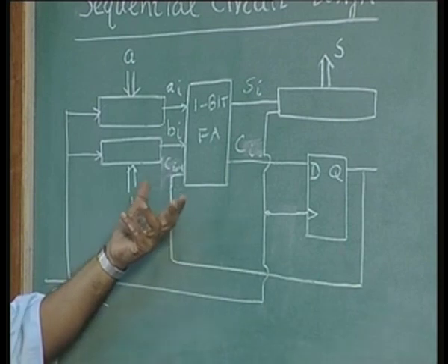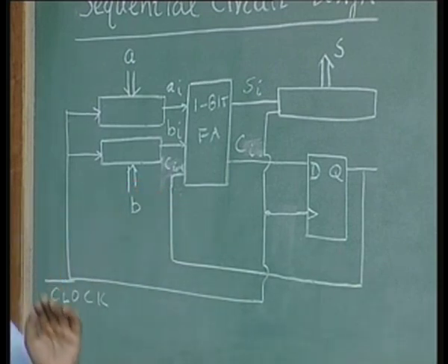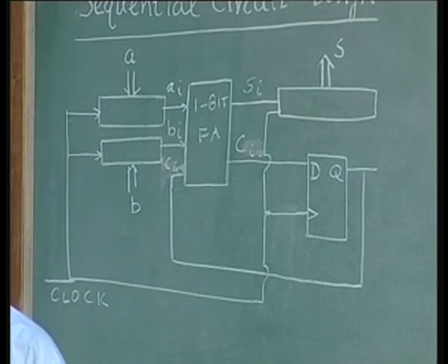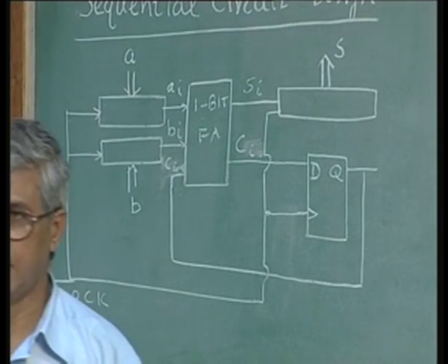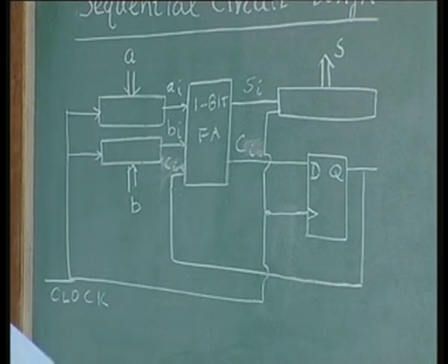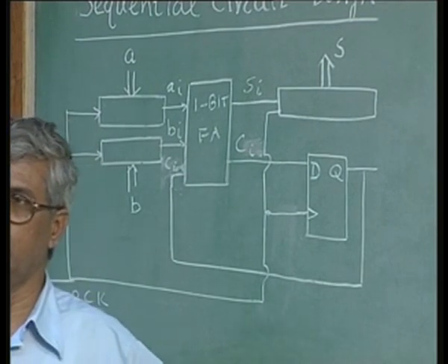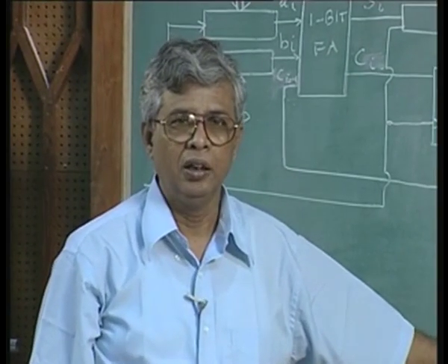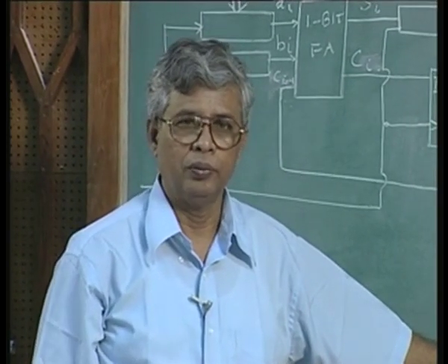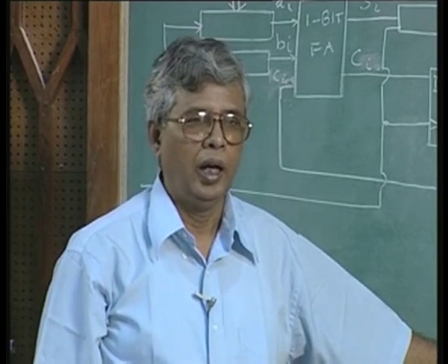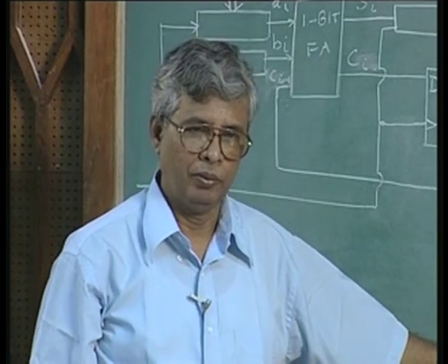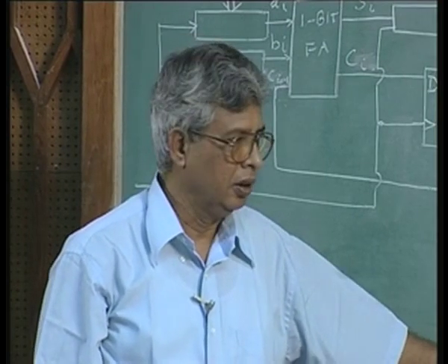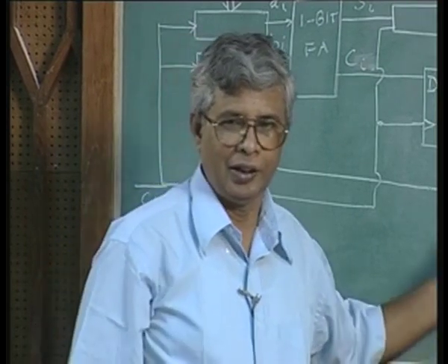I just brought this up because today, full adders are so inexpensive. A full adder consists of 2 exclusive OR gates for the sum and 3 2 input AND gates and a 3 input OR gate for the carry, and it is not huge hardware, and you can multiply it any number of times in order to carry out a large addition, plus the fact that this also delays the addition process.